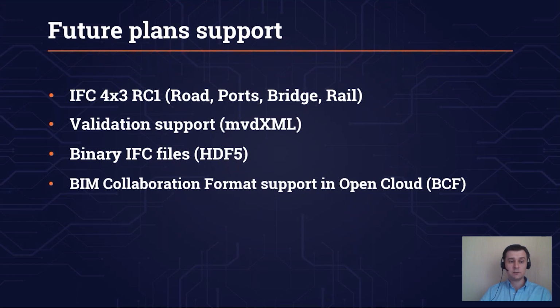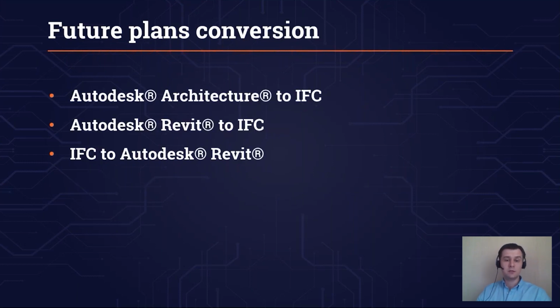And the other aspect is the conversion plans. Here we have three main aspects: Autodesk Architecture to IFC, Autodesk Revit to IFC, IFC to Autodesk Revit. Autodesk Architecture to IFC, this feature is in progress. Autodesk Revit to IFC is a more complicated feature and it requires more effort. And IFC to Autodesk Revit is a remote future plan. It will be implemented and investigated only after Autodesk Revit to IFC is ready.